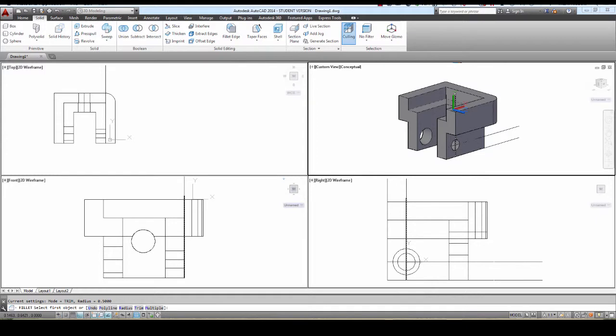Okay, so let's look at loop here. If we do fillet and we pick this edge again and do 0.25, and we do loop this time, we pick right here. Notice how it goes all the way around like that, and when I hit enter, nothing happens because that radius wouldn't work. You can't have 0.25 and 0.25 on a ½ surface. There wouldn't be anything left, so it has to be less than that.